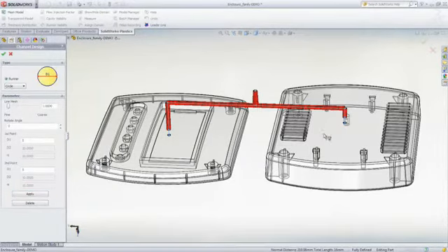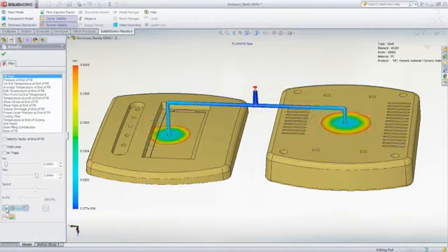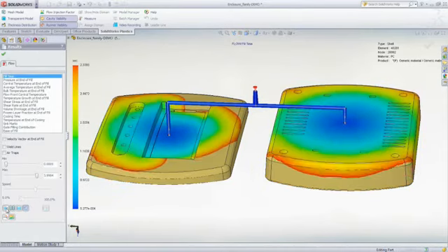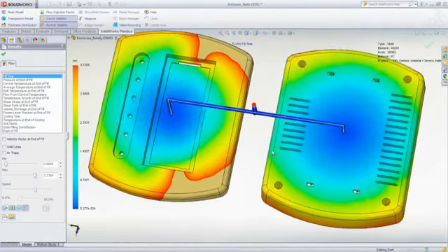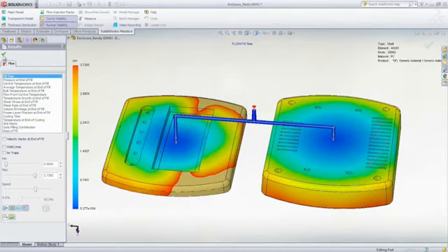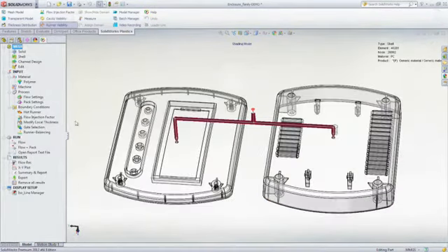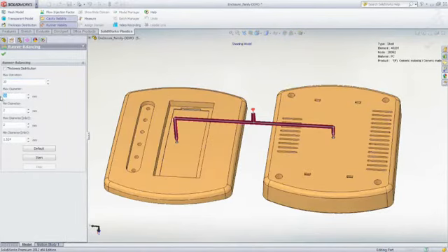However, an additional challenge is introduced because when you mold two or more parts of differing geometry in the same mold, your goal is to get all the mold cavities to fill at the same time. And this can be virtually impossible to achieve without the use of SolidWorks plastic simulation. The good news is that you can perform a runner balancing analysis in SolidWorks Plastics. This is a multi-iterative analysis with the objective of filling multiple cavities of differing geometry at the same time.